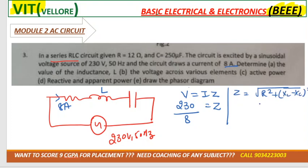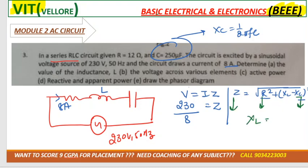Z value we obtain. R value they have given. XC we can get from C. XC is equal to 1 by 2 pi fC, right? So we know Z, only XL is unknown. XL we can get. After that, XL is equal to 2 pi fL, we can get L, right?